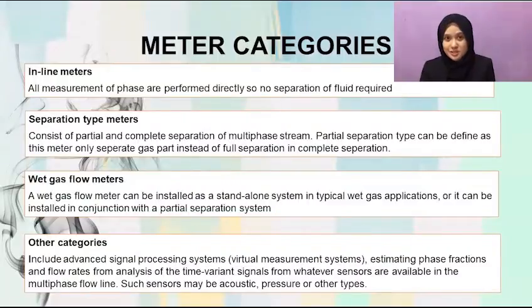So now I'm going to talk about the meter categories. The following meter categories can be applied to MFMs, such as inline meters, separation type meters, wet gas flow meters and other categories. For inline meters, all measurement of phase are performed directly to multi-phase flow meter, so there is no separation of fluid is required.